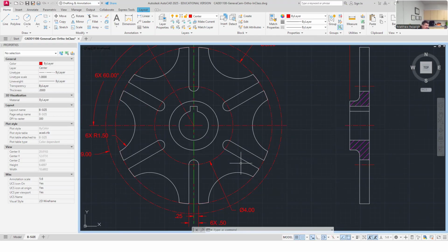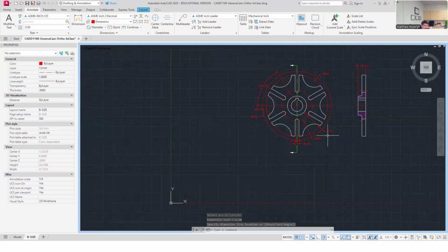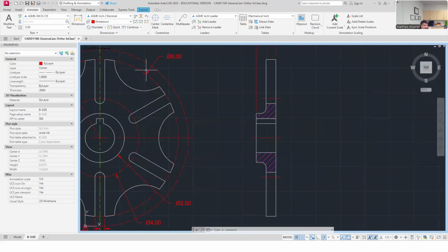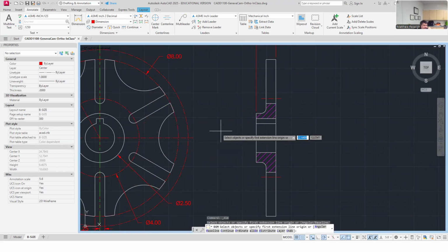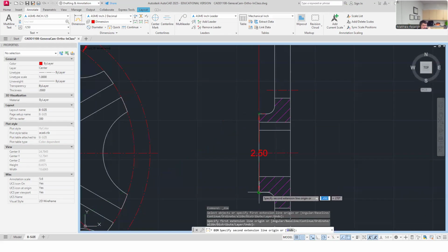That my cylindrical shaped feature, while I could point out somebody might just jump to this really quick and add this diameter and call that sized. I would say, well, I have it in rectangular view, so I think this one is a better situation where I'm going to pull this as a linear dimension for its diameter.